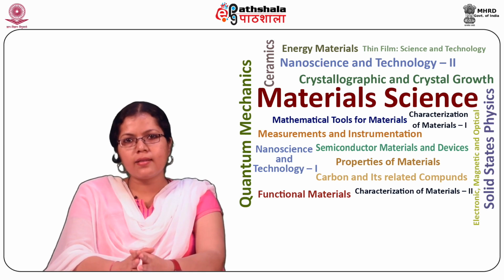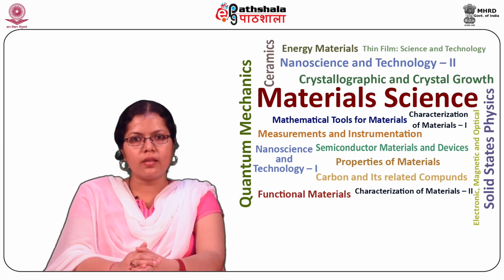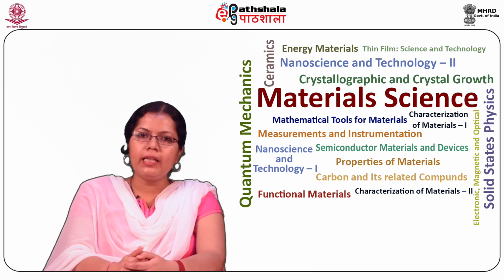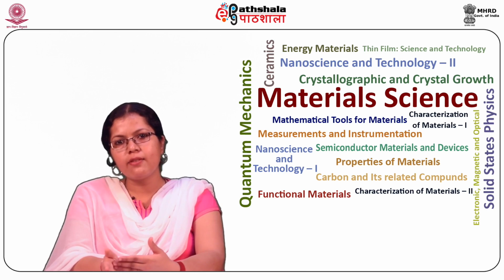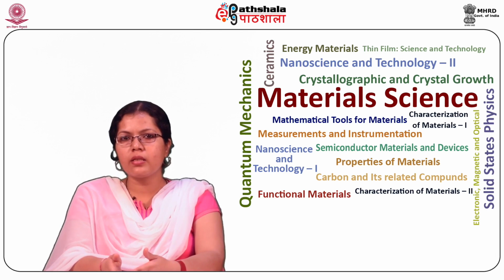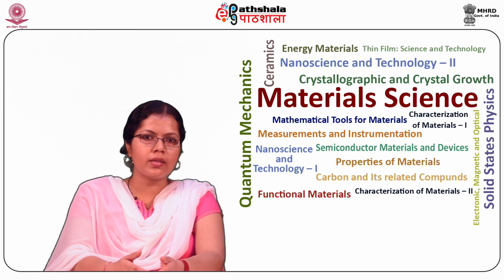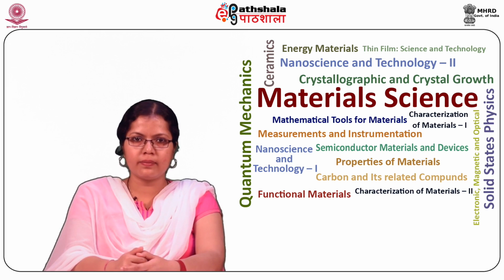So students, let us summarize what we have learned in this module. In this module, we studied about the Q factor of an electrical circuit. We learned about the Q meter, which measures the quality of passive electrical elements and circuits. Q meters are based on the principle of producing resonance with the element connected as required with a dual or complementary element and exciting the scheme with a variable frequency oscillator.